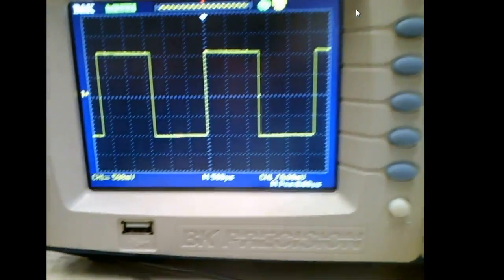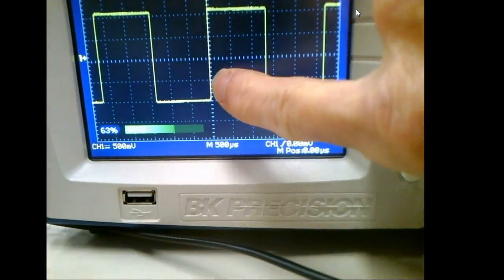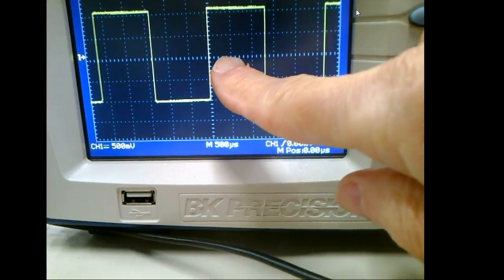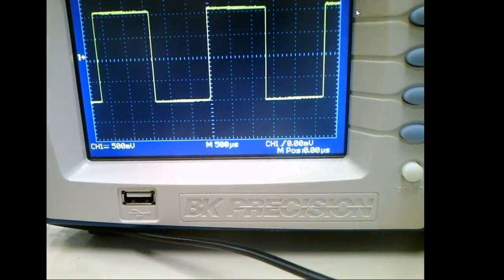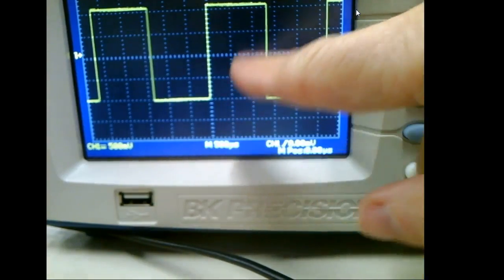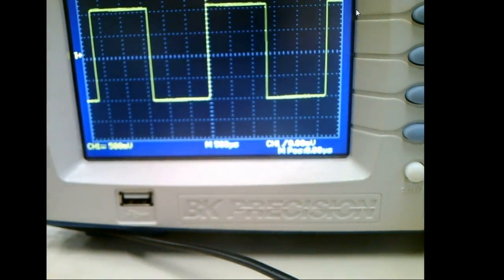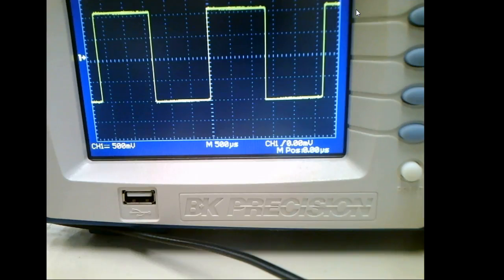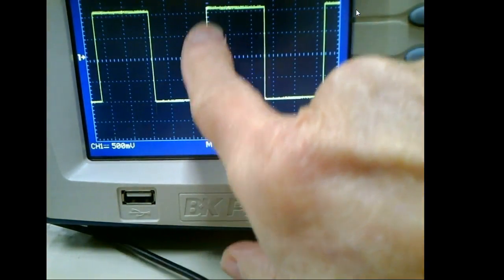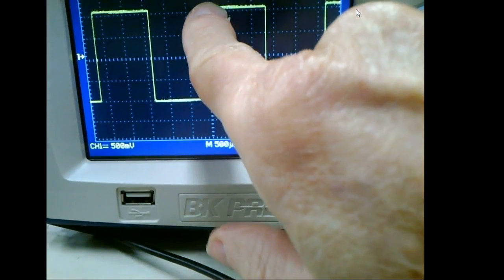When you say division, what is the division? These are the divisions, the big white lines. These are major divisions. These are minor divisions. So every major division is split into 5 minor divisions. So when I come down here and get this 500 microseconds, that's not for a minor division. That's 500 microseconds for every major division. Y'all understand? So if I wanted to know the time, first of all, I get one of my edges on one of my vertical lines. You'll see that?